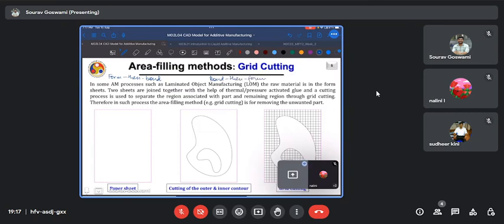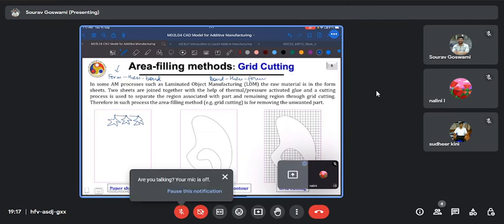Now, in form then bond, first we are actually printing our shape in each layer, and say I have many of these corresponding to each layer, and then I join them together by any means, such as by ultrasonication or others.